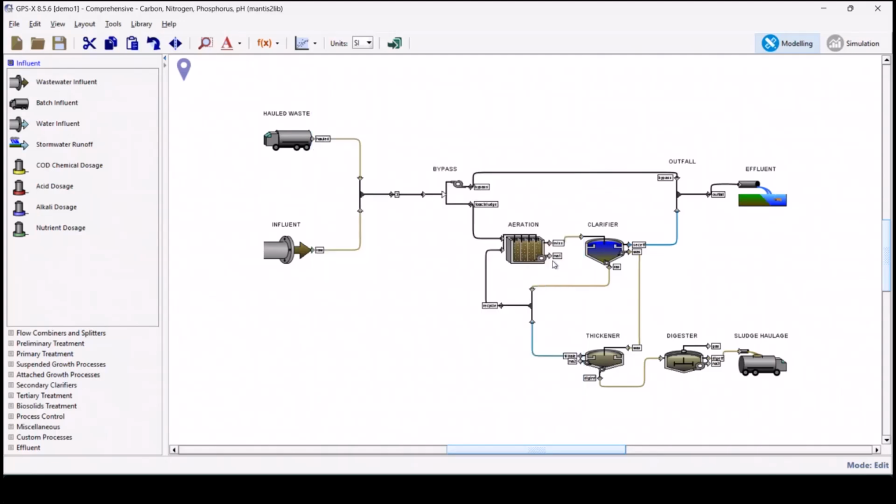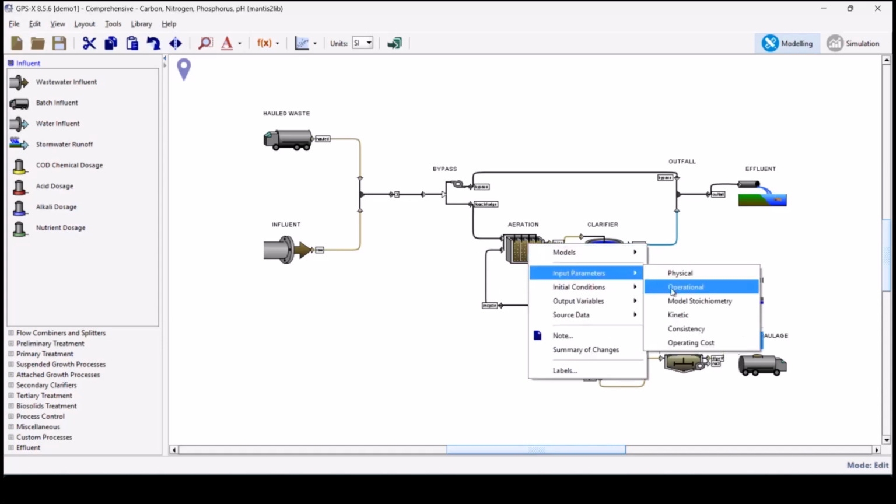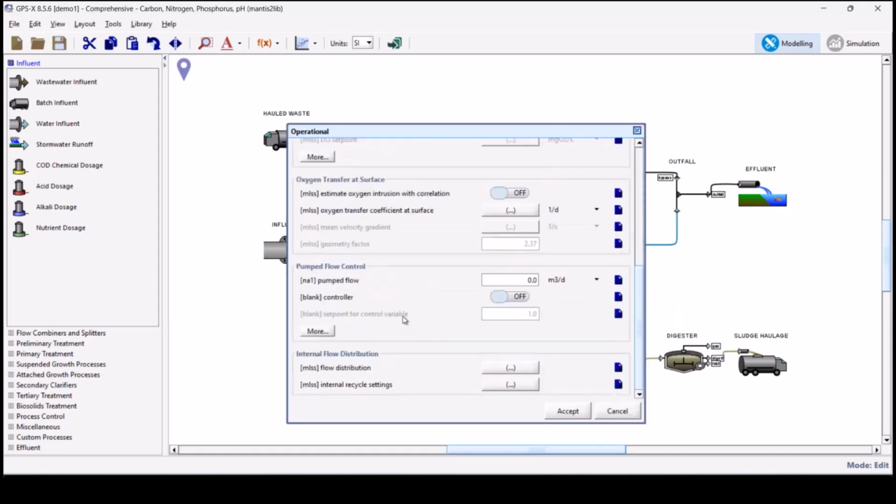And let's, for argument's sake, use this pump connection point here. I realize that's not common. This one's already been set up for an SRT controller, but this one has not been set up. So we're going to use this controller. Some people mix waste from their mixed liquor tank. Not all that common. And I'm going to go down here to that pump control menu.